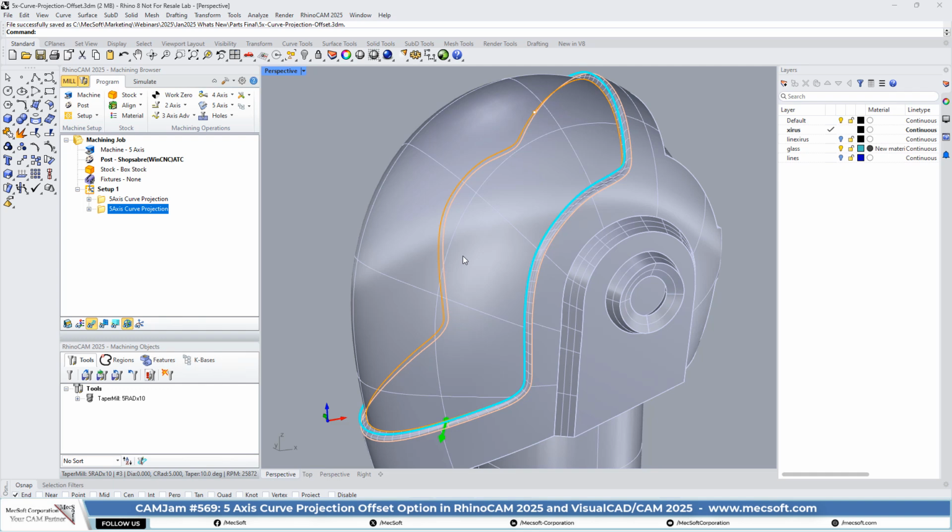Well, you can use a 5-axis toolpath. Just put that half-finished punched part on a fixture, and you can use this toolpath to go around and clean up those edges. In fact, they use this a lot with robotics to cut and trim things in 5-axis. In this particular example, it's a straightforward 5-axis continuous toolpath. In our 5-axis menu, it is the curve projection method.